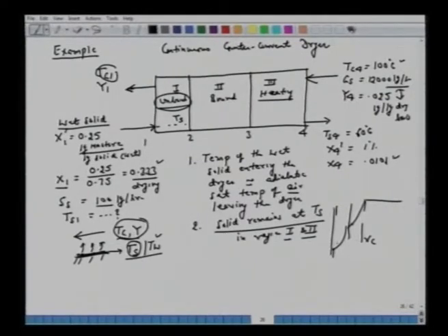So now we are talking of moisture which is being driven from inside. There it's a bit rigorous an assumption to assume that the solid surface temperature will remain at Ts. Nonetheless, that's an approximation that throughout this drying region, so regions 1 and 2, where we have this drying, whether bound moisture or unbound moisture, the solid remains at this Ts temperature. And this Ts is the same as the adiabatic saturation temperature of this air which leaves.